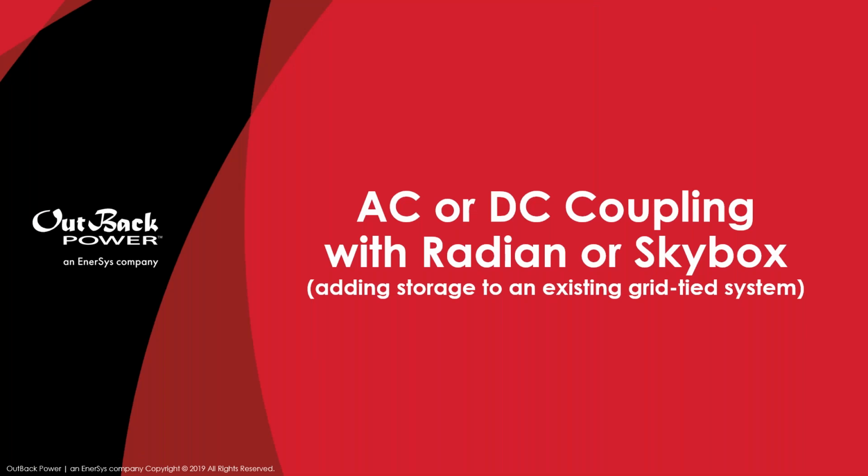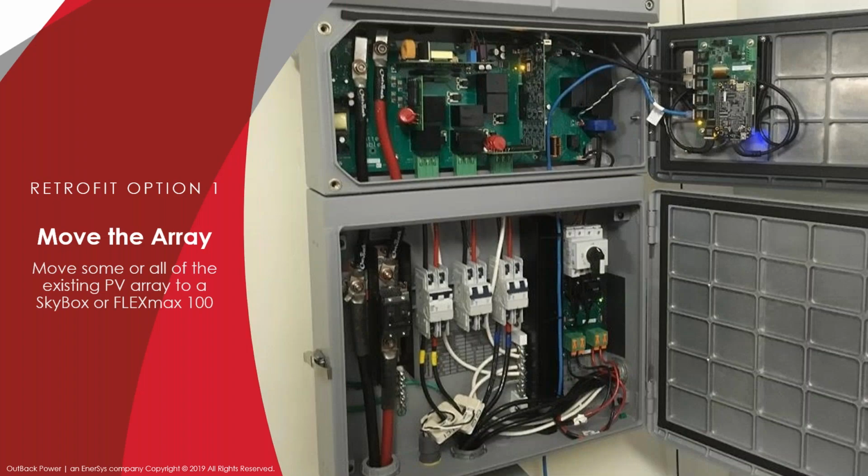Okay, so now we're going to talk a little about AC and DC coupling. One of the first options we're going to talk about is a retrofit option. You can see this is the balance of system load center portion of the Skybox inverter. And if you've ever installed a Radian, you can see this is a little bit cleaner installation, a little bit easier. This is the PV side. So these are the two PV inputs. This is the disconnect where these two inputs get combined into a single one, and then that comes up here through this little current sense into the inverter.